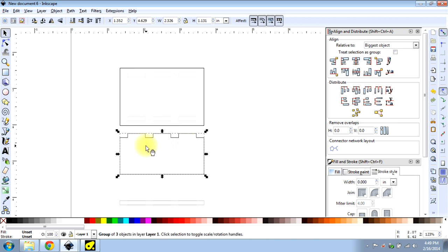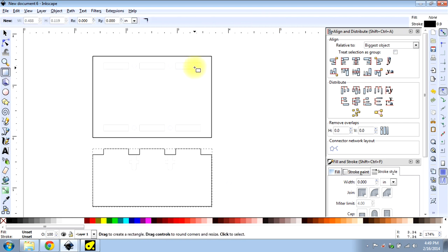And now you will notice that these three tabs will fit these three sockets. Those two T-tracks will fit these two screw holes. The screw will go through. The nut will sit there. They'll tighten together. And even though these are both drawn to identical measurements, the small amount of what they call kerf, the material that's lost during the laser cut, will make these fit perfectly well.